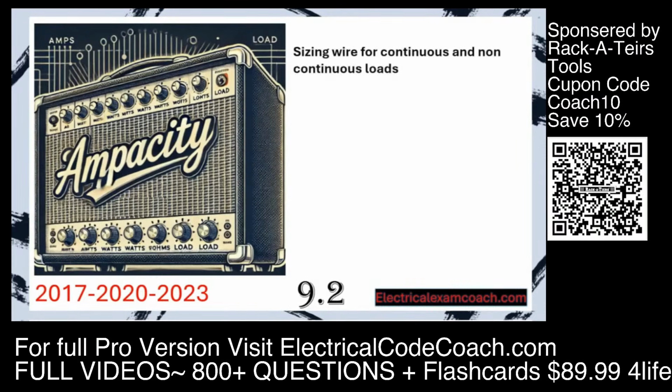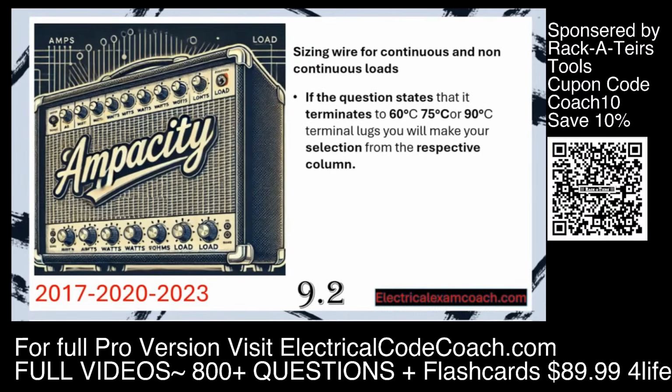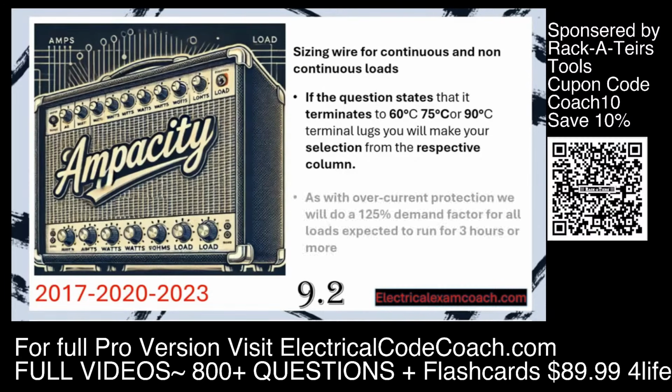In this lesson, we're going to be sizing wire for continuous and non-continuous loads. Let's recap on the basics before we get started. If the question states that it terminates to 60, 75, or 90 degree C terminals, we're going to make our selection from that respective column under normal circumstances. And the second one is, as with overcurrent protection, like we learned before, we're going to do a 125% demand factor for all loads that are expected to run for 3 or more hours.